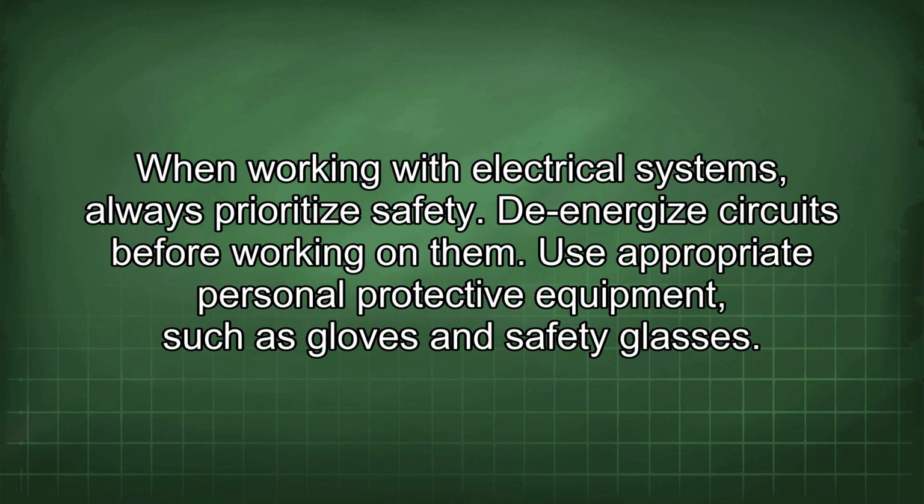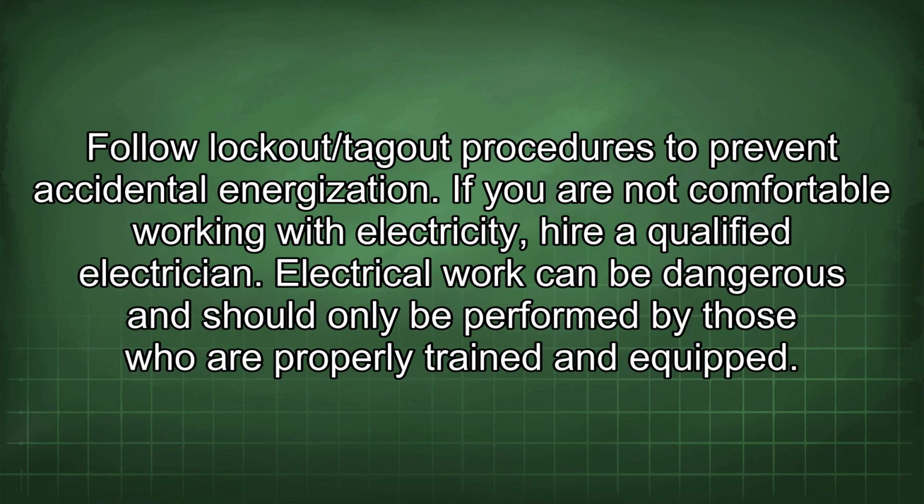When working with electrical systems, always prioritize safety. De-energize circuits before working on them. Use appropriate personal protective equipment, such as gloves and safety glasses. Follow lockout/tagout procedures to prevent accidental energization. If you are not comfortable working with electricity, hire a qualified electrician.